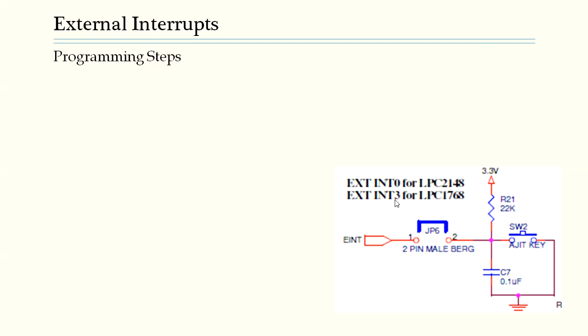Again, it's board specific, where we have the jumper connected as JP6 and there is a switch. The moment you press the switch, a path is set across. So when the external interrupt is provided to the input through this switch, this is how the connection diagram of the external interrupt looks on the ALS board of LPC1768.